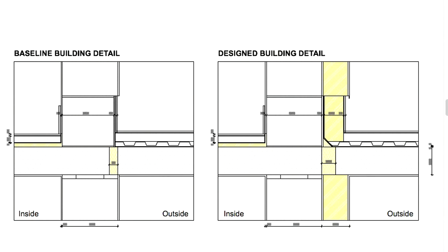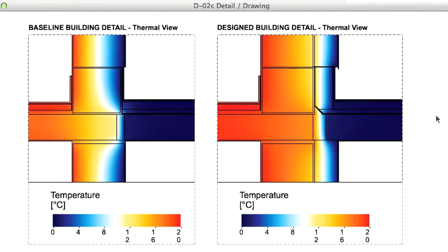the external wall. If the thermal views of the two details are placed side by side, the energy efficiency benefits can be clearly identified. In the advanced detail, the masonry block wall is protected from the dynamic effects of the external environment by the addition of a layer of thermal insulation. The thick thermal break at the balcony slab forms a continuous protective skin that envelopes the building. The masonry wall's external surface is less protected from temperature changes, and the thermal break at the slab connection is not thick enough to prevent the thermal bridge effect.